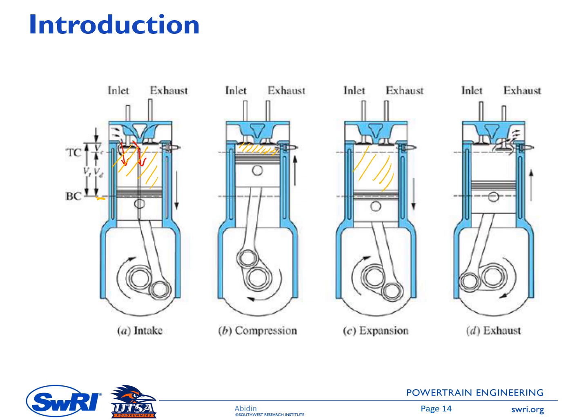And then the last process here is called the exhaust stroke. So the piston moves up and pushes the burned gas out of the combustion chamber, and the exhaust valve opens, you can see in here, and then the burned mixture exits the combustion chamber, and then the piston moves down again, going back to the intake process.